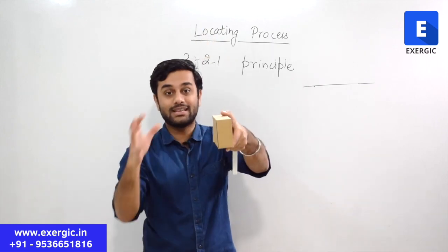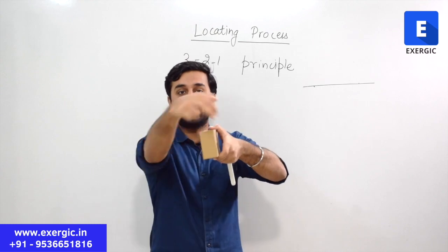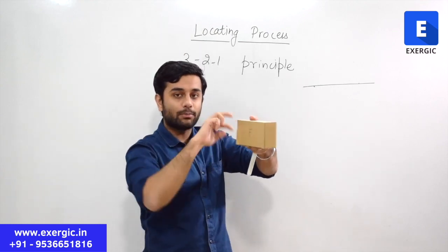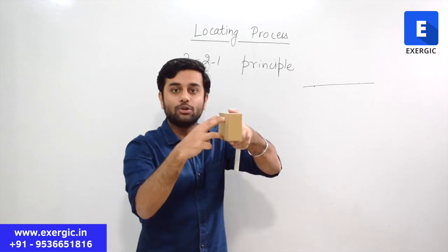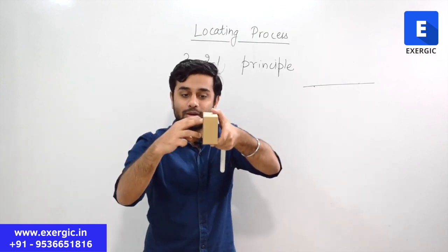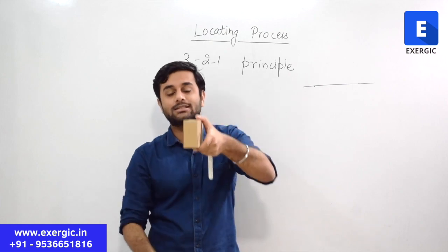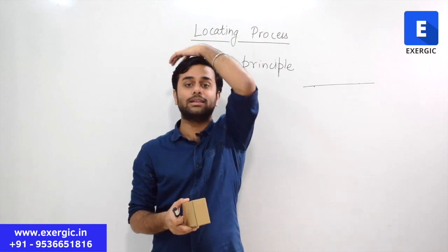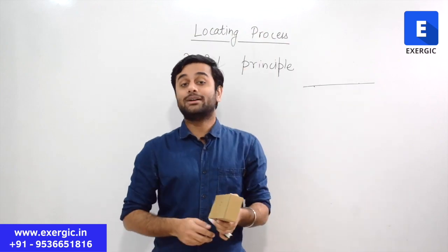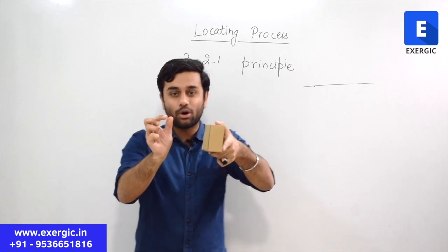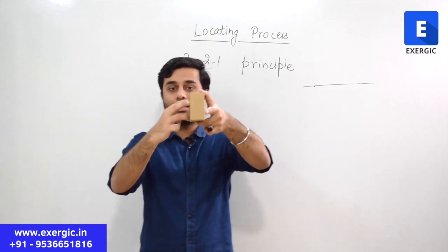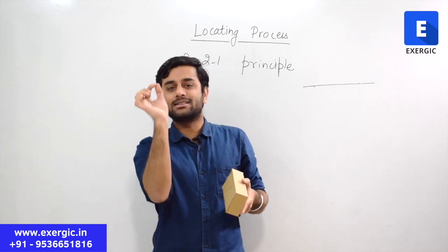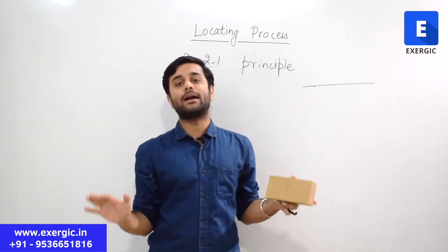This is the workpiece. Inside the jig, you have to support it. Then the tool will come and drill it. So you need to support it at different points. For the third point that you put, there is no guarantee that it will be on the vertical plane, just like this workpiece. So what to do? You cannot do anything. There will be some tolerances, but that variation will be very small, so you don't have to bother about it. Even if the plane is off the vertical by 0.01 degrees, it does not matter.